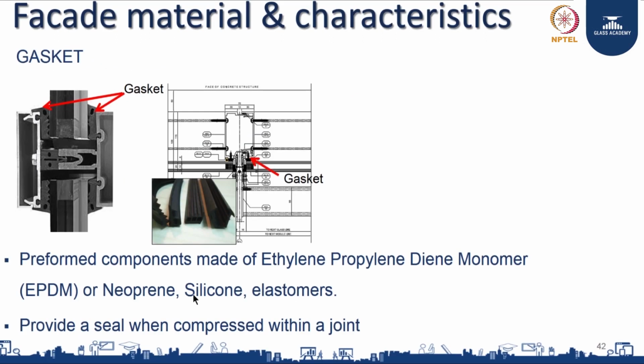Now we talk about gaskets. What does a gasket do? What is a gasket? Any materials, when you put them together, there is abrasion and you have to separate them. If you don't separate metal to metal, what will happen? They will start making noise. They will start binding together. Sometimes, if excess heat is there, they will merge together. So we have to keep them separate, at the same time taking care of a little bit of expansion and contraction in different directions.